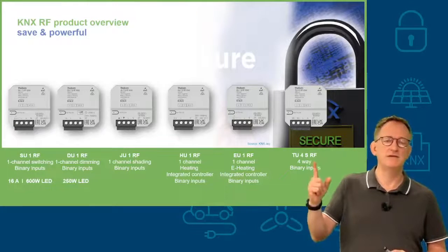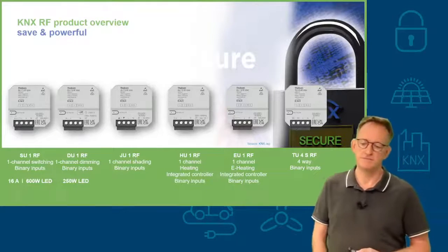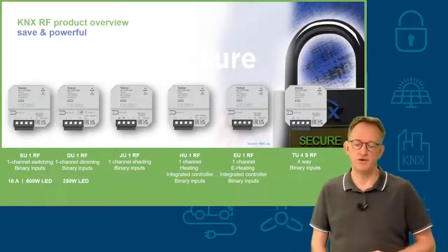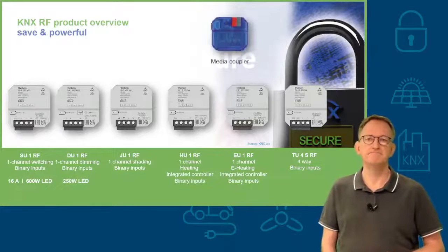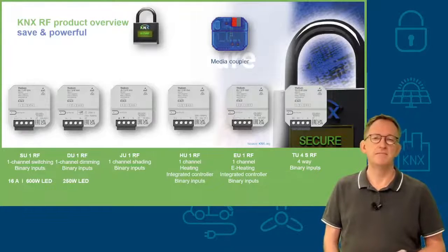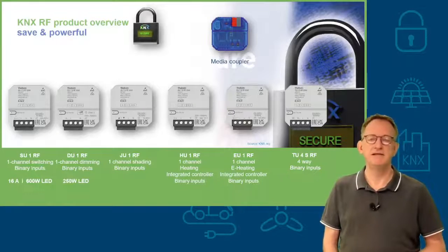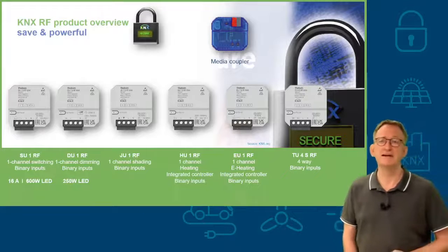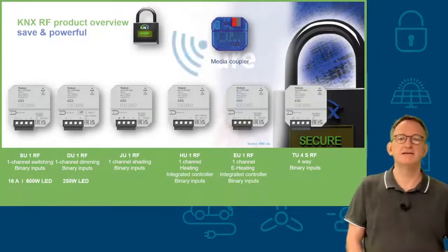And we have the TU4, which is a 4-way binary input. And for sure the media coupler, as I have explained, which is necessary to communicate between the TP line and the RF devices. And as I have mentioned, all of the devices are KNX Secure.